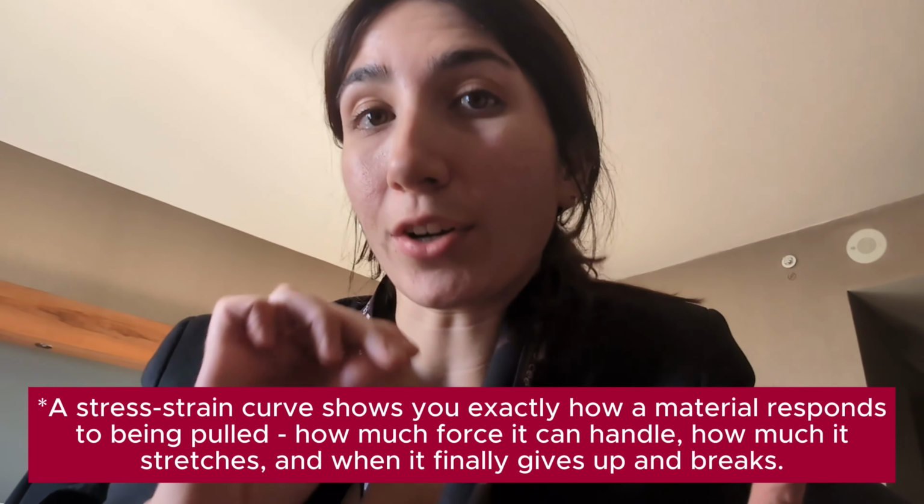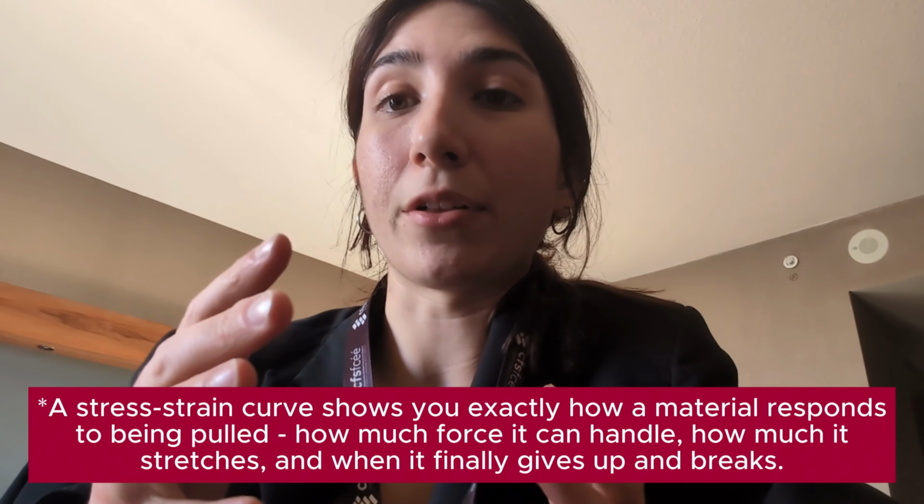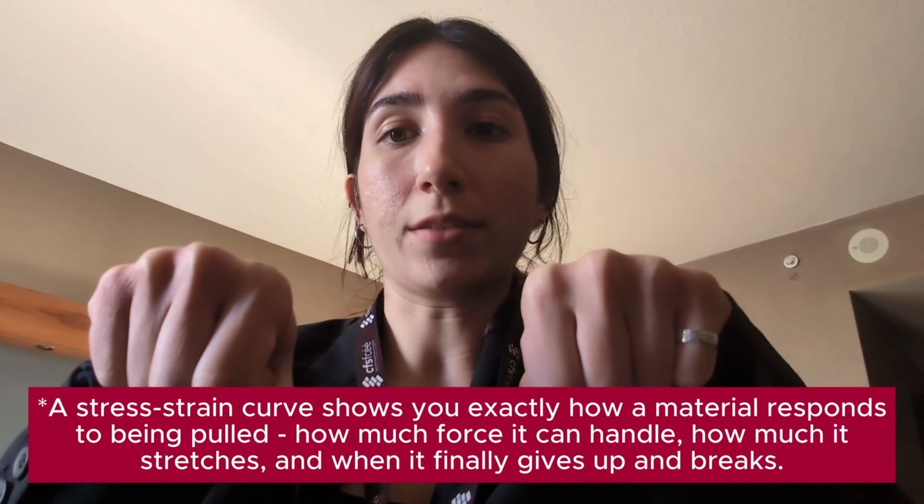And so the key point here that I'm trying to highlight, especially through the stress strain curves, is that approximating stretching or strain of a material using the actual moving parts of the machine that are performing the test means that you're measuring everything in the system. But when you use an actual extensometer, you're measuring only that material. You're not measuring how the machine is moving, and you're able to actually capture true behavior when it's being pulled in that tensile test.